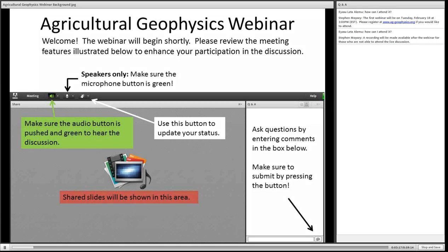We wouldn't be mapping any EC effect of the metals themselves because they're bound up and don't really enhance the current flow too much. What we can do is map the salts and acids, the dissolved solids that have invaded the pore spaces and, in some cases, bound themselves to clay particles, which would increase the conductivity.